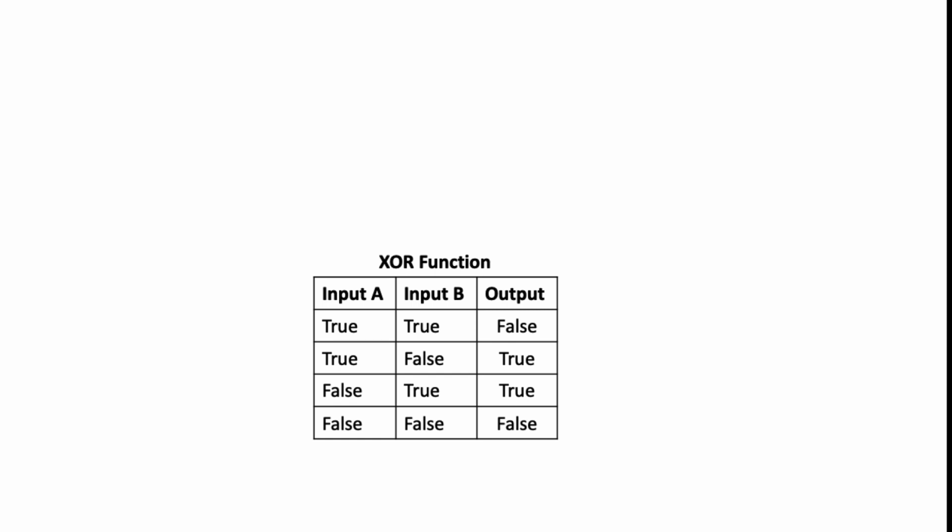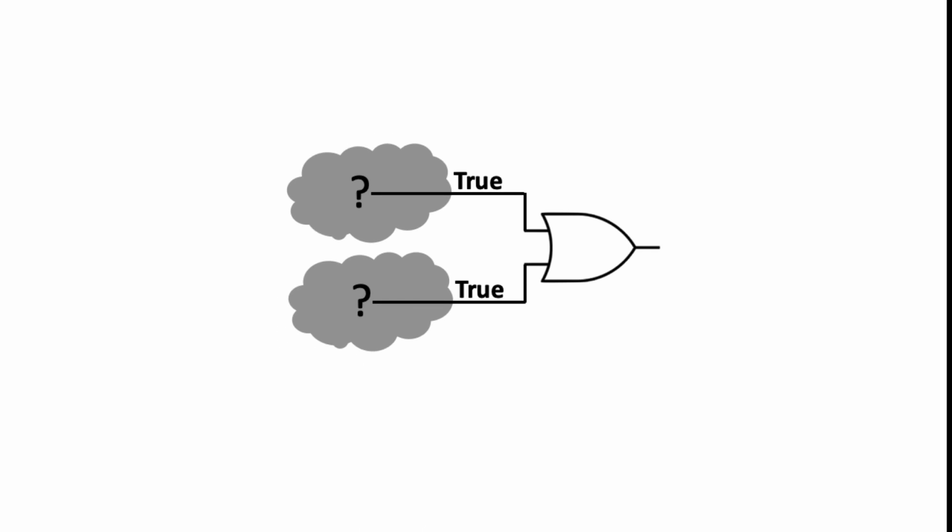As Boolean functions become more complicated, it becomes more difficult to figure out the logical schematic. One simplifying approach is to consider building schematics for individual outputs. We only need to consider those outputs that are true. If we can figure out how to build schematics for each of the true outputs, then we can OR these schematics to create the final result.